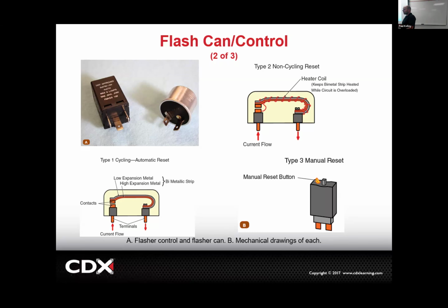So if it's an old school car, you can probably still hear it in your mind, the actual ticking sound. It was that. New car, we don't do it like that. We're going to do it more like a solid state. It's really going to be an electronic flasher. We can even use the control module to do it. We'll just put it on a timer circuit, and that solid state flasher no longer has to heat up and cool down. It just says on, off, on, off.